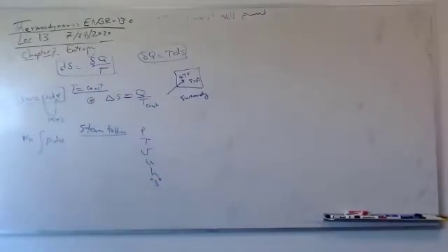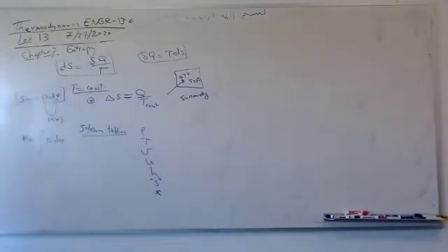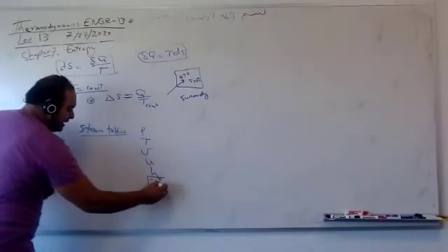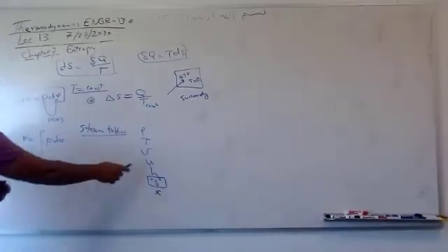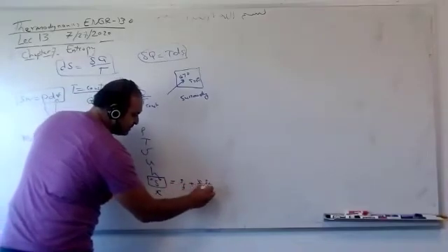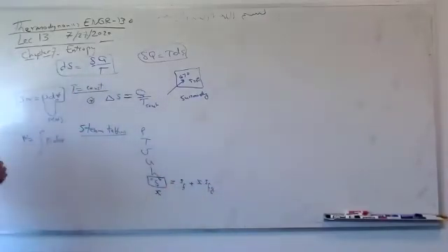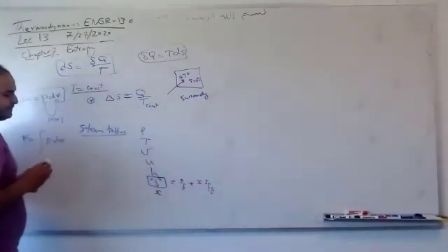And we're going to see today how good or important this property is. Of course, we also have x, which is quality, only if we have a saturated mixture. So this new property is the last 3 columns in the steam table: sf, sfg, and sg, the same way you use u, uf, ufg, h. For example, s equals sf plus x sfg if you have quality, if you have a mixture. So you can get quality from here or use quality to get s.